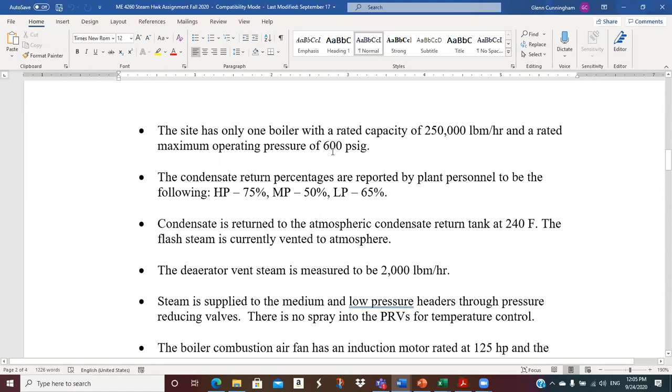But if all I have to do is increase the settings on the boiler, maybe replace some safety valves, then I could operate it. Probably wouldn't go clear to 600. Maybe you go 550, something like that, not push it clear to the top. That might help you on your turbines. Something to think about.